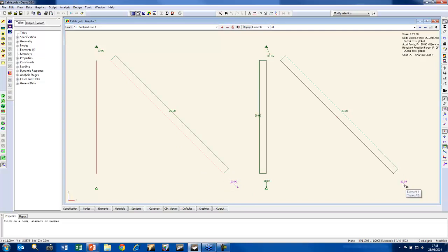Whereas with cables, the load goes up around that support and back down to here, to the end of that chain of cable elements, giving quite different results. As these nodes along the chain act more like pulleys than fixed points, if you were to try doing a continuum model with the nodal loads along the length, you will find they will slide into the middle, giving you a V-shaped deflection, not a continuum, which might not be what you want. But there are times when cables are very powerful and very useful.